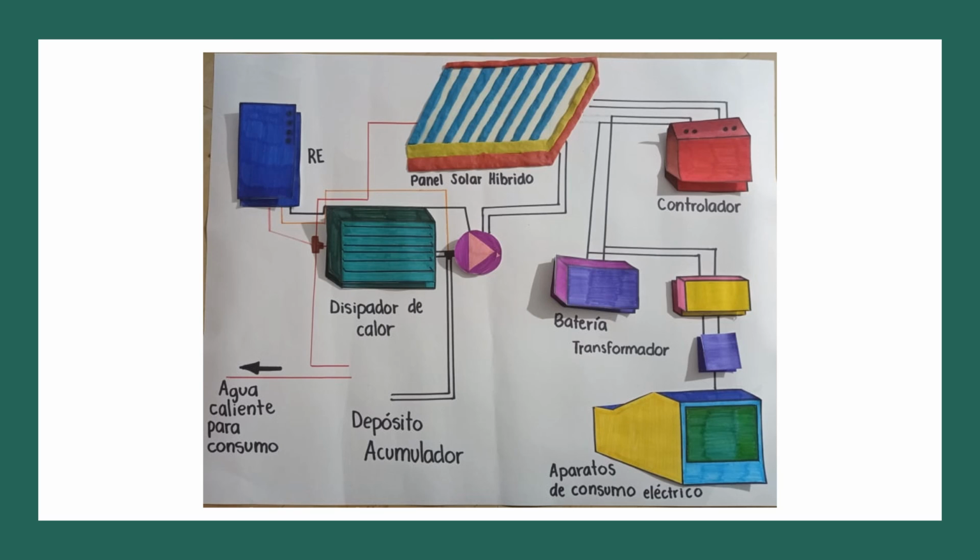The experimental validation of the results obtained in the different simulations requires a test facility that allows simulating the different operating conditions to which the system will be subject. This type of installation will allow measuring both the thermal and photovoltaic production of different prototypes, being able to vary the most influential parameters for performance, such as the flow of circulating fluid, the impulsion temperature, and the inclination of the panel. With this, the aim is to be able to test the different prototypes in different scenarios.